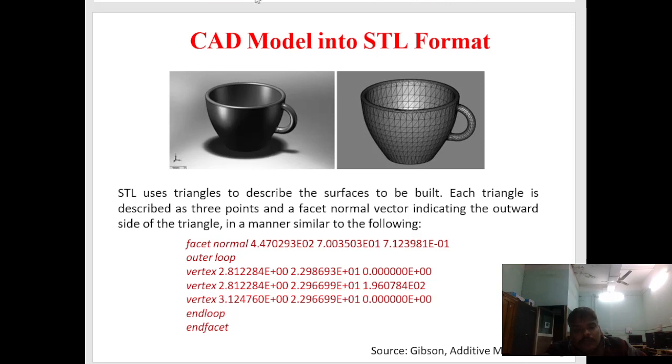First you have to make the design on which you want to do the analysis. After that, you have to provide the property of the material. What are the property of the material? Then you have to provide the boundary condition, which end is fixed, which end is having the load, and this step is the meshing. What happened in meshing? We discretize the whole model into small elements.